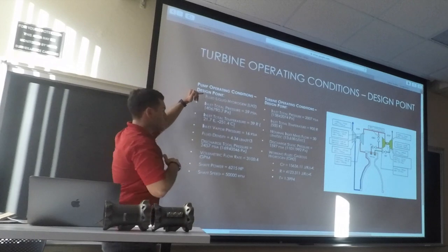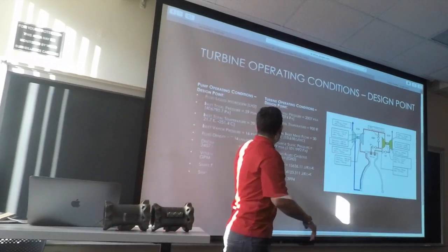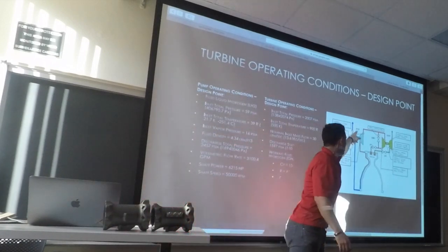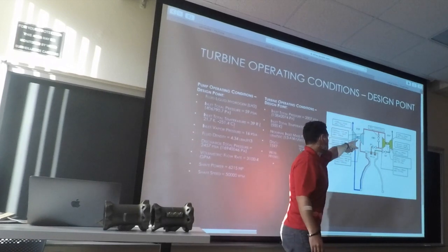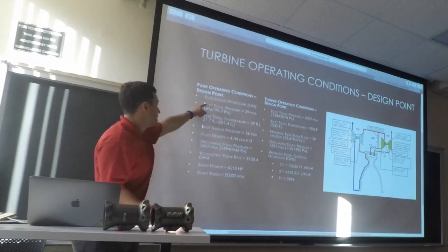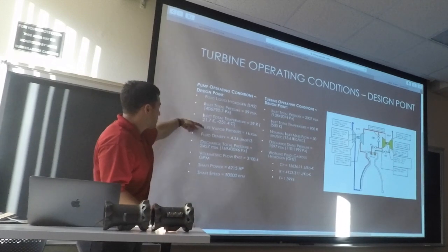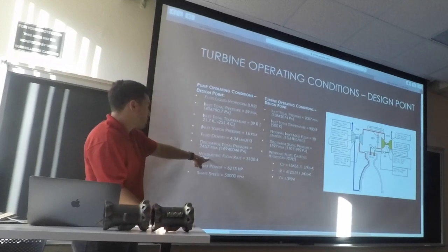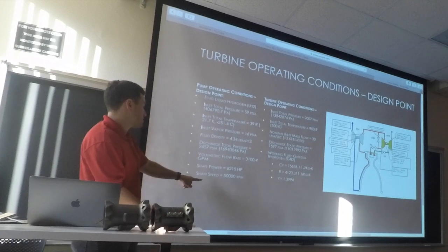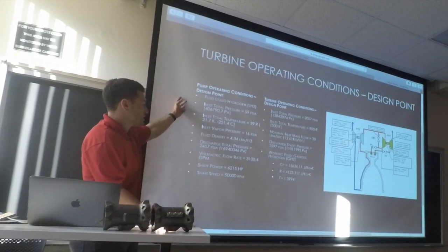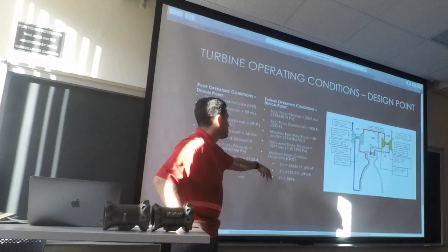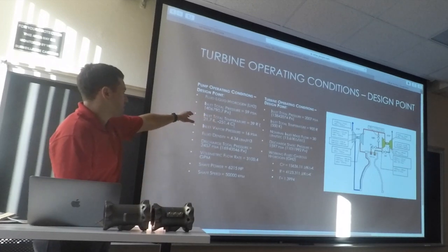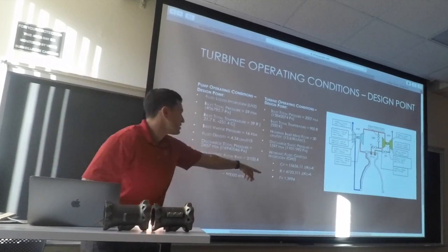So, all right, we're concerned with making one of the pumps. Which one did we use, the aux or the fuel? I don't remember. It was the fuel. The fuel. So this is the fuel turbo pump, the aux turbo pump. Build the turbine for that based off of these conditions. What the inlet pressure is, the inlet temperature is, vapor pressure, density, discharge pressure, right? This is what you need to get. This is what the tanks are. Volumetric flow rate and how fast the shaft is and how much power it needs to produce. And then the working fluid, what the properties are for it, mass flow, temperature, and so on. Oh no, this is the pump and the turbine. Yeah, sorry. So what the pump is, what the turbine is. You needed to take this and then make it.